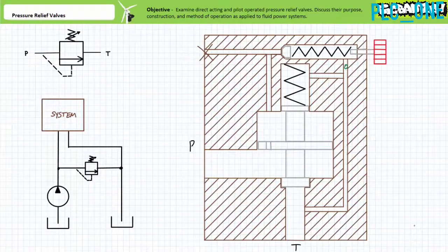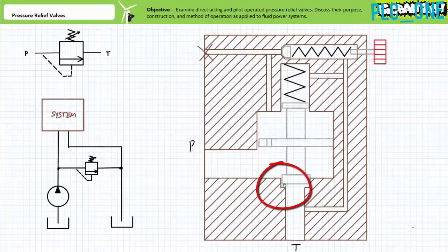Somewhat less nefarious, consider if a contaminant got semi-permanently lodged between the valve body and the primary spool. In this scenario, the pressure relief valve would constantly leak a small quantity of fluid, regardless of pressure, and actuator speed would slow, since a portion of provided flow is continuously diverted. A pressure relief valve exhibiting such a continuous leak might be warmer than expected.